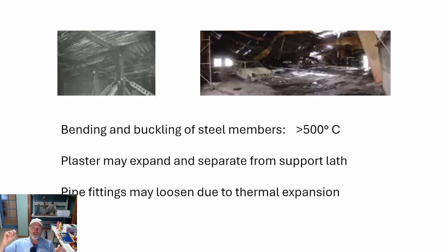Now a lot of people assume that's only because of the applied load. And there's definitely applicability to that conclusion. But there's one other major factor that's often overlooked: differences in thermal expansion between the bottom flange and the upper flange. Keeping in mind, let's use as an example a 100-meter long I-beam. Just using these as rough numbers, you're not actually going to see that. Now, if I raise that by 1,000 degrees, based on the coefficient of expansion for steel, I'm going to see a 1 meter expansion on that beam.